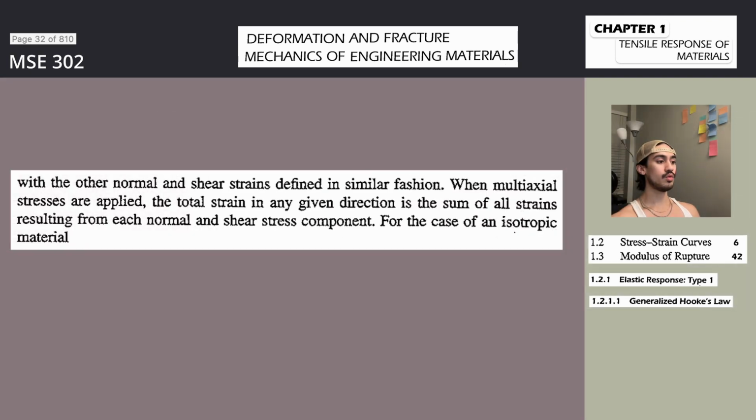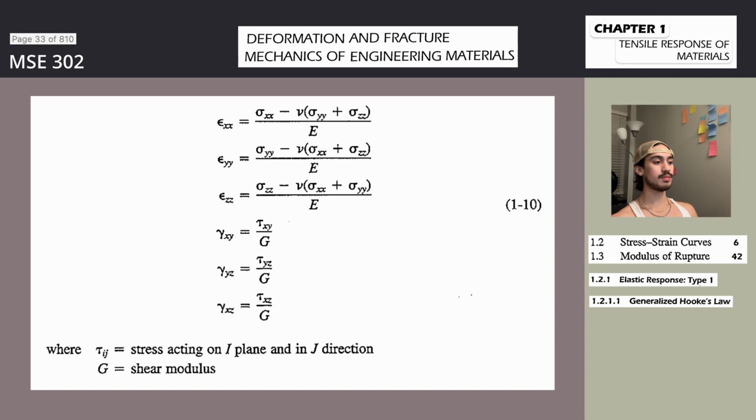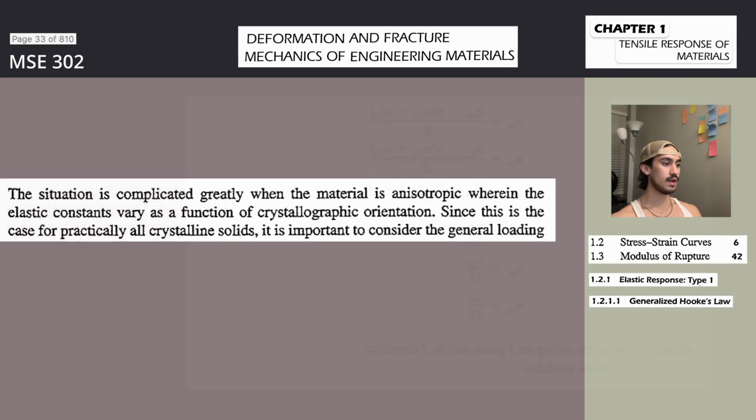The magnitude of the strain hardening coefficient reflects the ability of the material to resist further deformation, and may be equal to unity, which represents ideally elastic behavior, or equal to 0, which represents an ideally plastic material. Selected values of strain hardening coefficients for some engineering metal alloys are given in Table 1.5. Note that n values are sensitive to thermomechanical treatment. They are generally larger for materials in the annealed condition and smaller for the cold worked state.